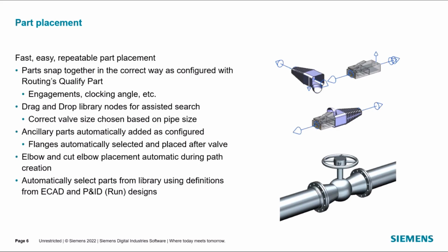One of the things that you'll notice is that the parts will have these arrows coming off of them. Those represent connection points, and we call those ports in NX routing. So we have a process that we call qualification. Qualifying parts is what we do to add these connection points, these ports, so that you have parts that come together. So maybe two connectors might fit together, or you have wires going into a terminal or into a connector in specific ways. So those ports help to define those.